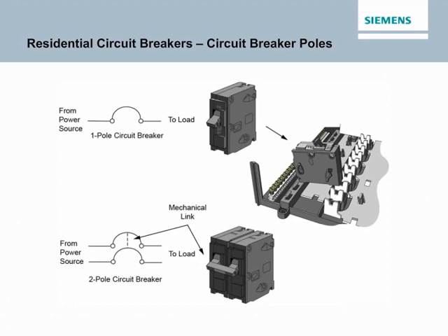Residential circuit breakers are typically 1-pole, 2-pole, or 4-pole breakers with current ratings of 225 amps or less and voltage ratings of 120 volt, 120/240 volt, or 240 volt. Because residential circuit breakers are also used in commercial applications, and many commercial applications require 3-pole breakers, some 3-pole breakers are also included in this category. Residential circuit breakers are normally plug-in types that mount in load centers or other enclosures.